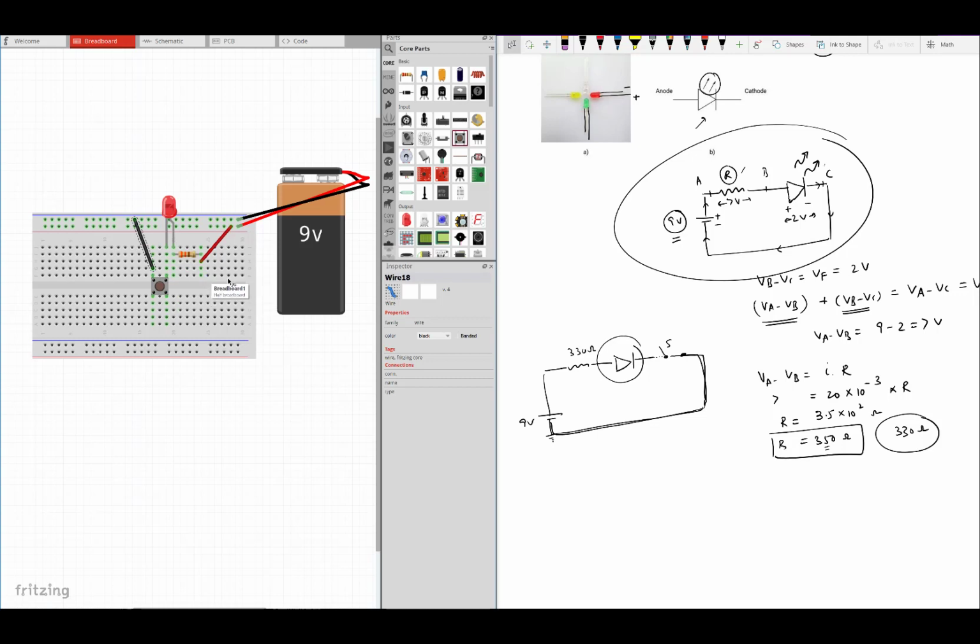So if I want to introduce any other element, let's say I want to introduce a photocell in this circuit, right? So let's say I wanted to get rid of my switch. I select it and press delete, and over here in my circuit, I'll replace this switch with a photocell. A photocell basically acts like a variable resistor, because when more light falls on it, its resistance goes down. When less light falls on it, then its resistance goes up.